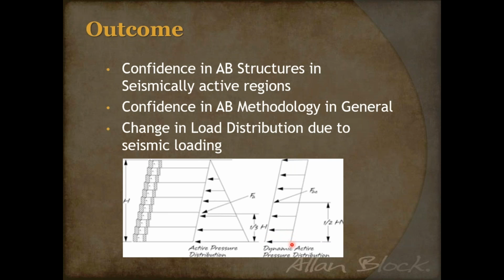The old thought process was you had very little pressure at the bottom, but you had a maximum pressure at the top. So I wouldn't say a complete reverse of the active pressure, but it was a much higher pressure at the top of the wall. Kind of like that flagpole whipping effect is really what they thought about in the original concept. Because of our testing, we've proved it over and over and over again that that dynamic load is more uniform. It changed the methodology, which was great. Now all of a sudden we've got something more accurate than what was originally thought of. So it's a great way to advance the industry.